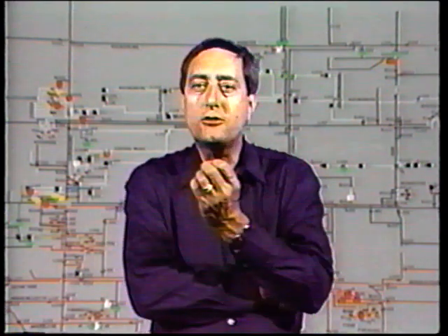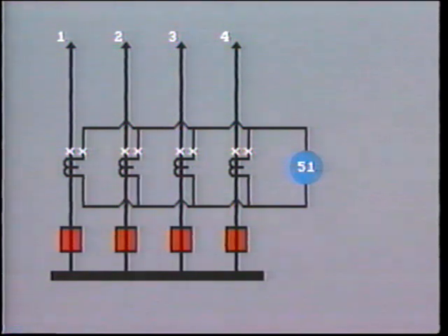Another method of providing high-speed differential bus protection is by the use of high-impedance relays. Actually, this type of protection offers more than just high impedance, as we shall see. Let's go back to our simple current differential that we have already discussed. As we know, one major problem with this relay is that it may inadvertently trip for external faults due to the transient surge when the fault is initiated.